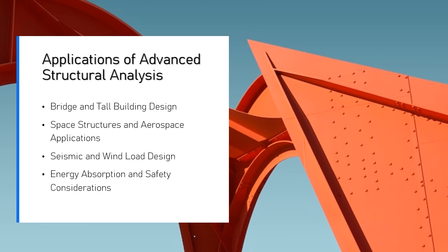Outcome. These energy-absorbing systems reduce the kinetic energy transferred to the bridge, minimizing structural damage and improving safety for travelers. Additionally, impact-resistant materials help prevent long-term degradation from repeated low-intensity impacts.